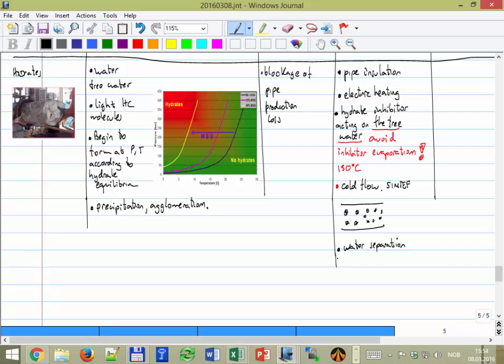And also remember that the water, as I explained before, is not all the time in liquid form, but it might condense along the pipe. So you separate it at some point, and then as the temperature drops, you are going to get water that is condensing. So you still might have the problem. So you really need a kind of subsea drying process of the gas.